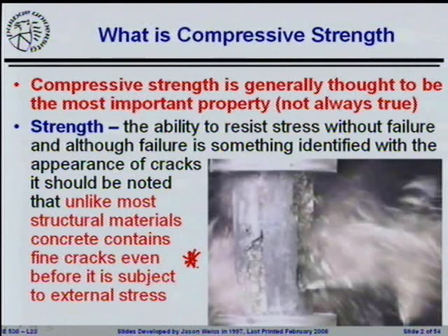If you make a concrete cylinder, you set it out into the lab, you put a stethoscope on that and you record it over time, you will detect cracking. We do that. We use a very fancy stethoscope called acoustic emission. We listen for cracks. They exist. They're present. It is a composite material, so this happens. You will get lots of cracking even before you get up to the peak strength.